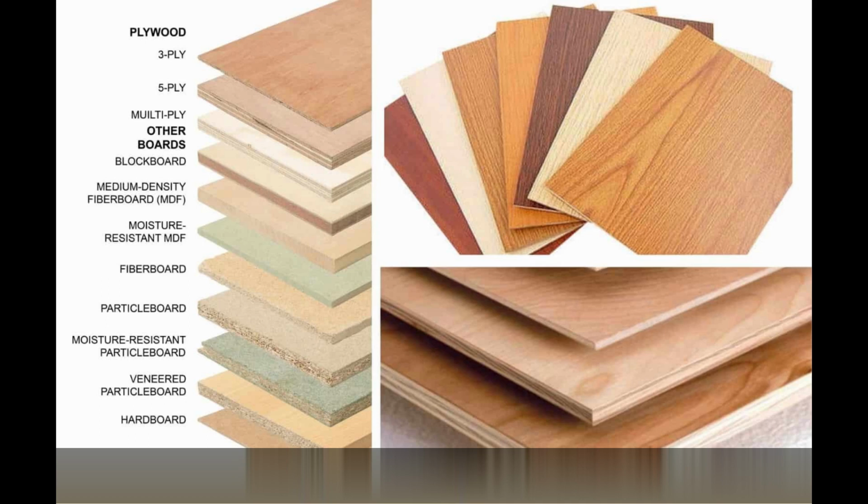This prevents one board from moving up or down relative to its neighbor, providing a solid feeling floor when the joints do not lie over joists. Tongue and groove plywood is usually found in the 13 to 25 mm range. This type of plywood is often prone to splintering if not handled correctly.